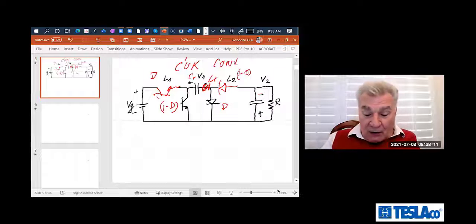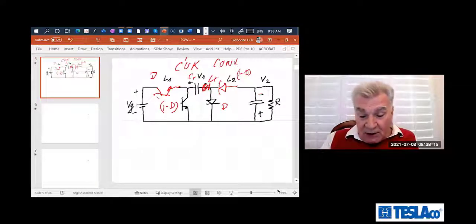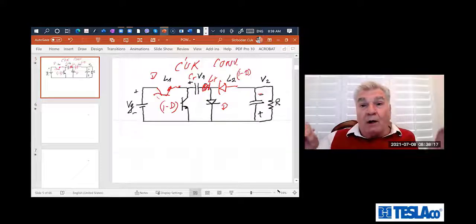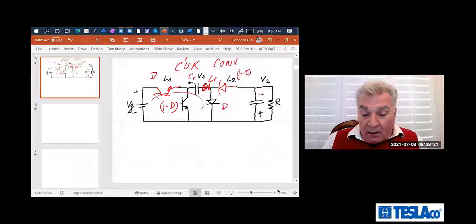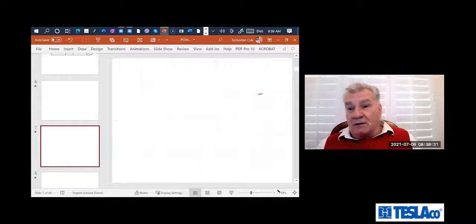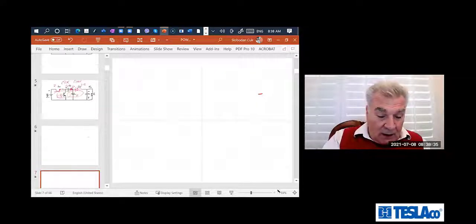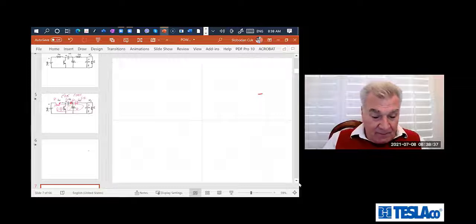Because of this resonant inductor, just like I showed in the hybrid switching, it will get volt-second balance during on time only. And then, when this switch is turned on for 1 minus D, there is a resonance here. The same inductor and the same capacitor create a different resonance. I mean, the same resonance, but in a different part of the interval.